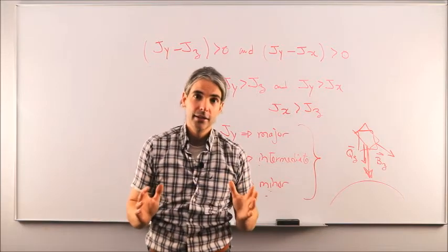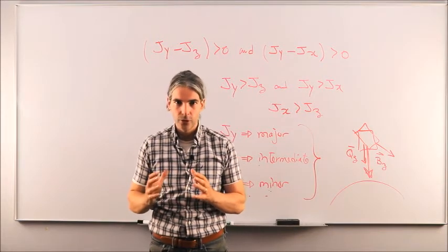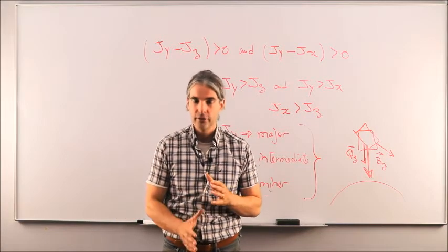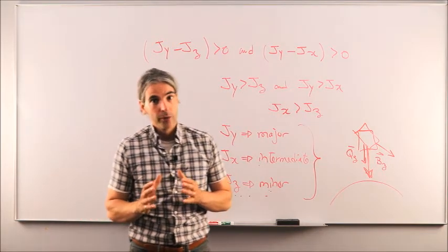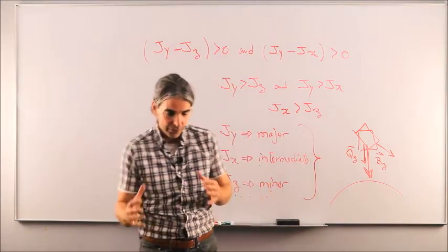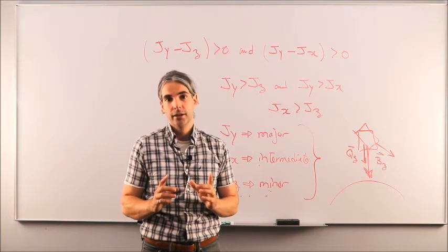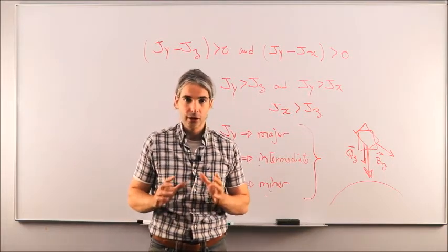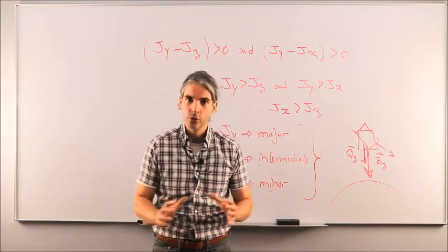So for small CubeSat applications where we want to always have the camera facing down at the Earth throughout multiple orbits, this is a cheap and easy way to maintain the orientation of the spacecraft in that configuration. Now, that would get perturbed on orbit because, you know, drag is there, solar radiation pressure is there, magnetic torque is there. So all those effects have a torquing effect on the spacecraft. Not only is gravity gradient acting on the spacecraft, which means that we're going to get roll and pitch angles equal to non-zero values at all times, right? It's going to swing back and forth, but still that swinging motion will remain stable.